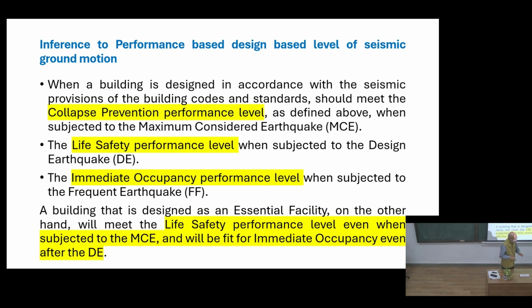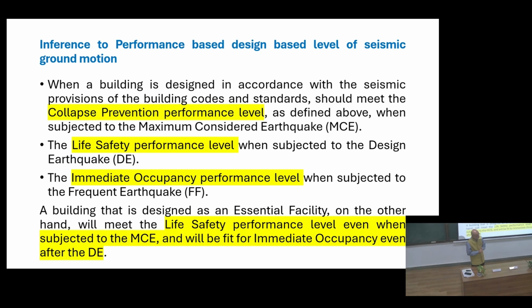So when we design a structure, even the site-specific condition we assess. Scientific studies are carried out, and if required, we can scale up the ground motion, or synthetic ground motion is also generated, and based on that we can say the maximum likelihood of earthquake at a place. So MCE is a very important parameter.